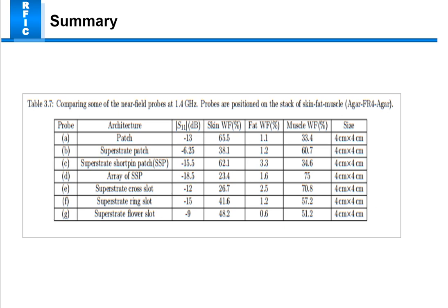The designs are validated with the FDTD commercial code and measurement, and the near field pattern of the circular patch with the superstrate and shorting pin is measured as a reciprocal. And you can see in this figure there is a comparison, and almost eight architectures are mentioned